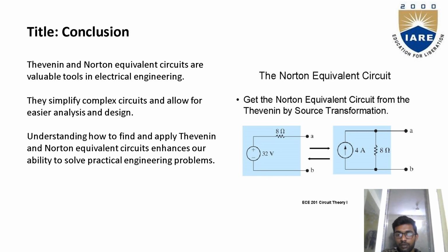So by these two methods we can solve easily, by finding the equivalent voltage and equivalent resistance, and we can put a load also. Understanding how to find and apply Thevenin's and Norton's equivalent circuits enhances our ability to solve practical engineering problems.